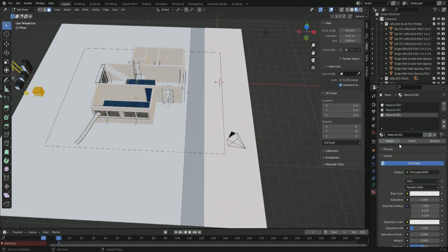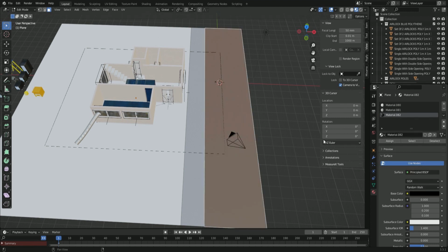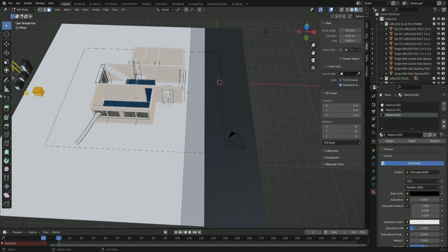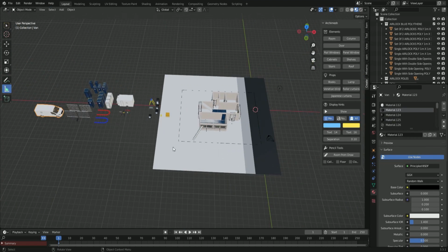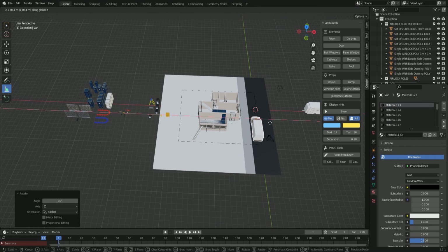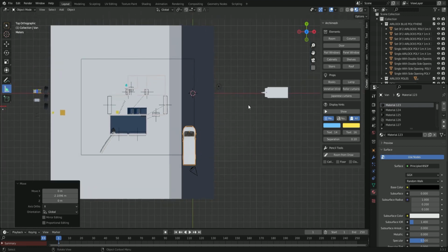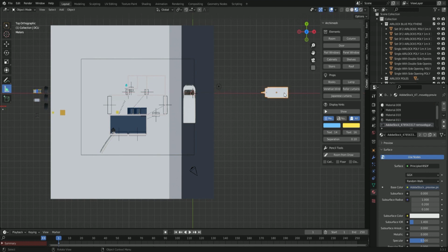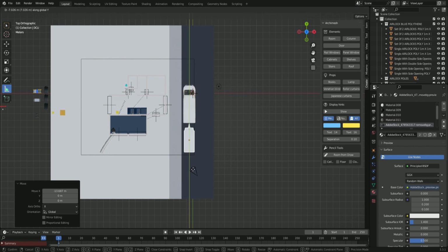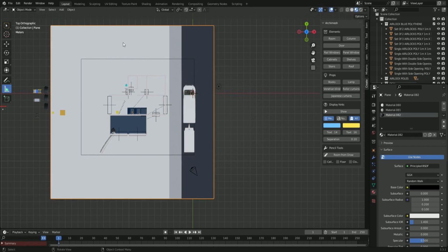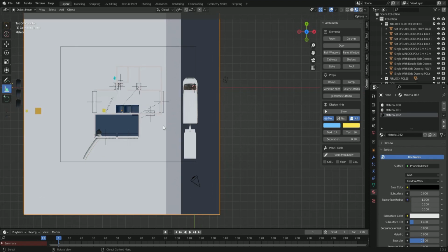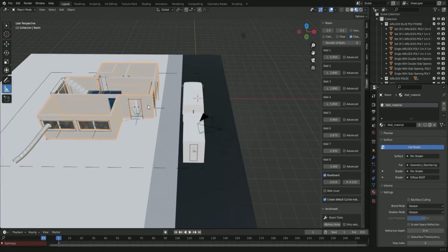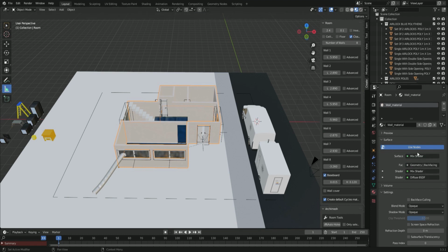And then Control R will bring up, if you move your mouse around, you'll end up getting a line going right down the face. Just tap that, move it along, make a loop cut, go on the other side, Control R, find the horizontal line, tap that, move it along. Then you can go to the top left, change into faces mode. Then because we've loop cut these, we can tap on each of the faces and change the colors.